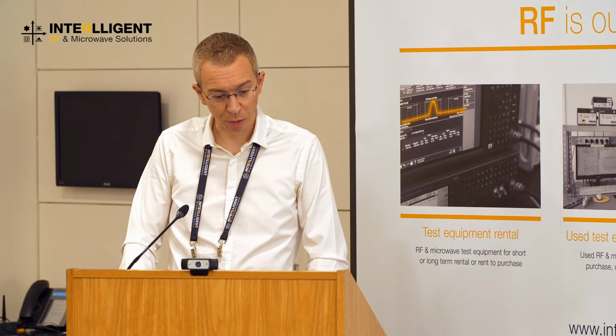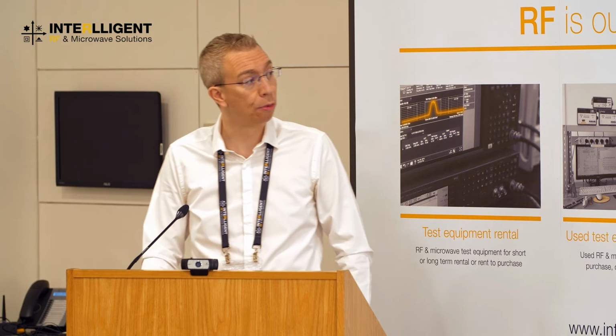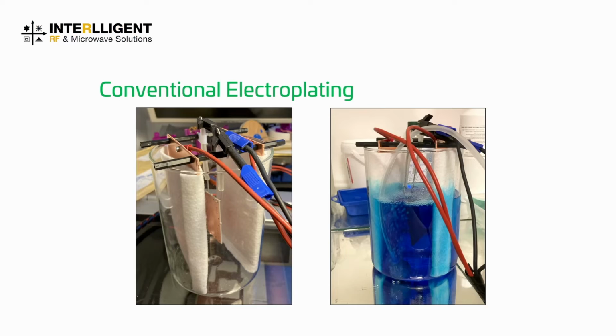Once that's done, quite simply, we put it into a conventional copper electroplating bath with 2 anodes either side of the PCB. And in about half an hour, we can add 17 to 35 microns of copper over the full surface and all the via holes.